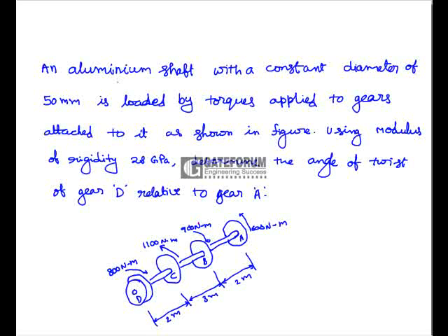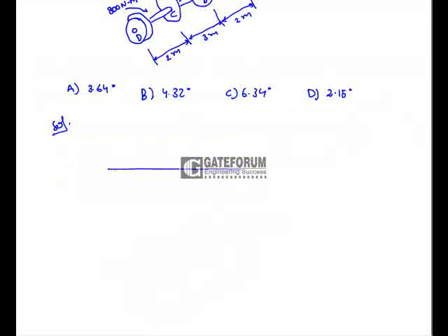Here first we will have to find out the torque variation between A and D. So here draw a torque variation diagram. First consider a zero line. So this is a reference line. Now consider anti-clockwise torque as a negative value, and clockwise torque as a positive value. Here 600 Newton meter is anti-clockwise, so draw a line down below the reference line. So it is 600 Newton meter.